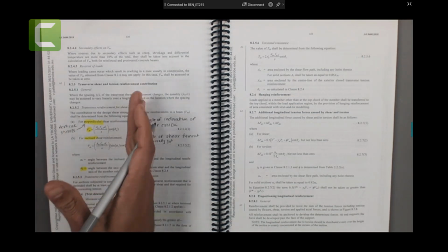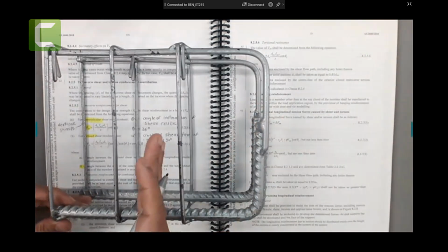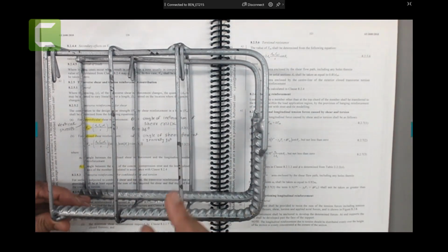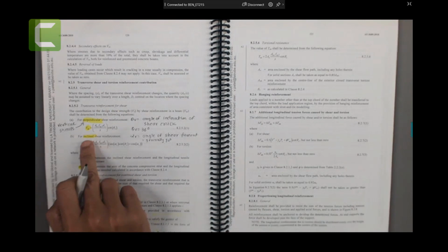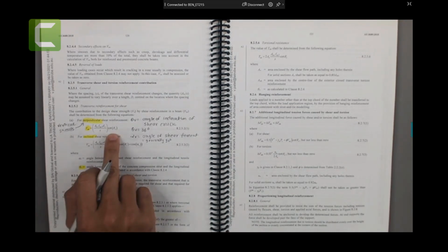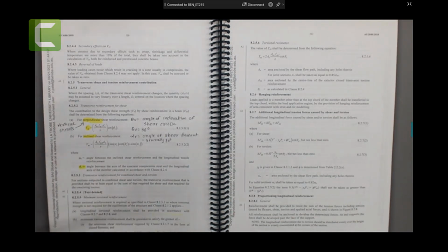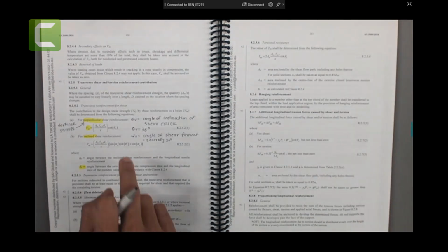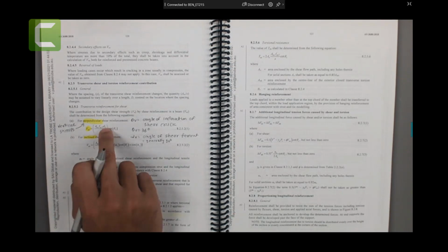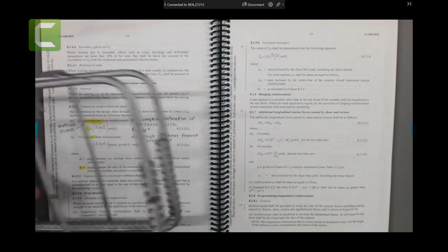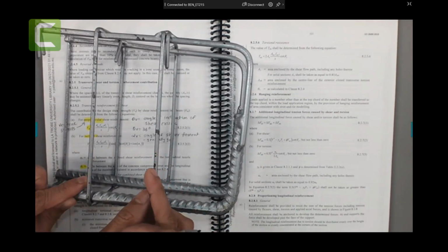For perpendicular shear reinforcement, as I mentioned, we are perpendicular. This is perpendicular reinforcement, right? If I put it here, these are your perpendicular reinforcement. They are not at angle, so that alpha V equal to 90 degree. And if you have an inclined shear, we need to use this equation, but we have these values. ASV, area of your fitments. FSY.F, the yield strength of the fitments. dV. S is the spacing, meaning the space from one bar to the next fitment, from center to center distance.